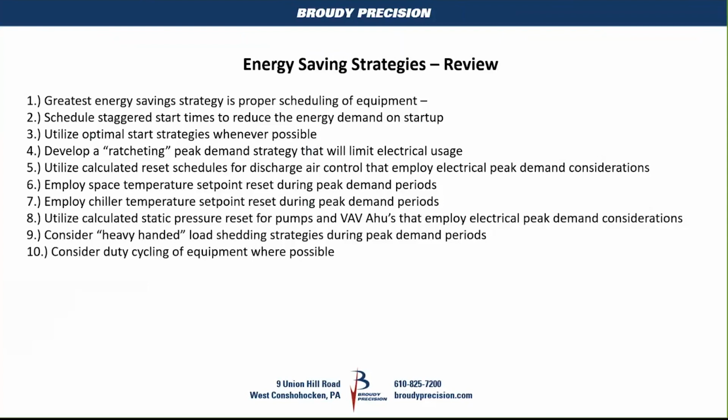There are other energy saving strategies, like optimal start. For those of you that don't know what optimal start is, it looks at the start time of a particular air handler, for example, or a zone, and says, hey, you're 5 degrees out of set point. Optimal start looks at outside temperature, inside temperature, and our start time, and calculates through a little algorithm how much time we actually need to start that piece of equipment up before the people get there.